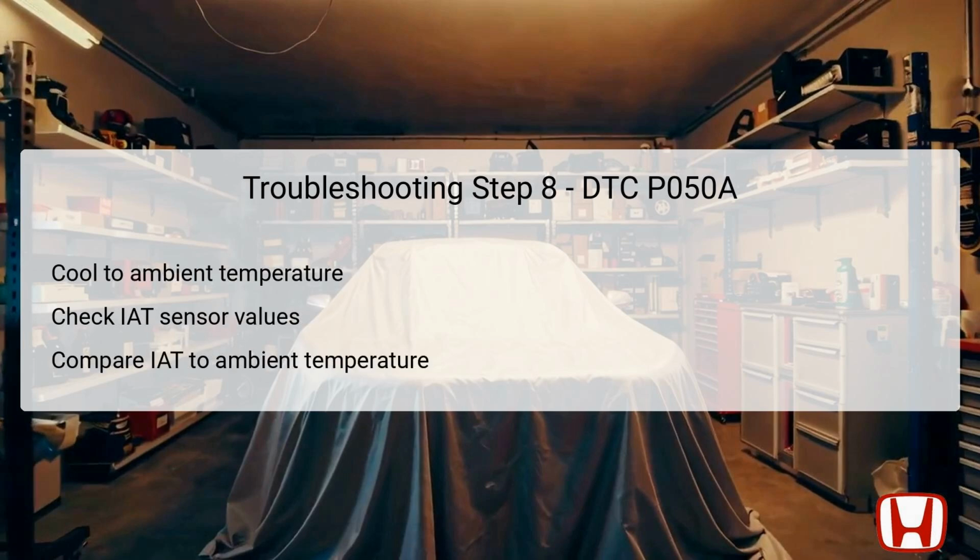The last troubleshooting step involves assessing the intake air temperature (IAT) sensor performance. First, cool the engine to ambient temperature before turning the vehicle to the on mode to observe the IAT sensor's value through the HDS data list. It's essential to compare the noted IAT value with the ambient temperature.